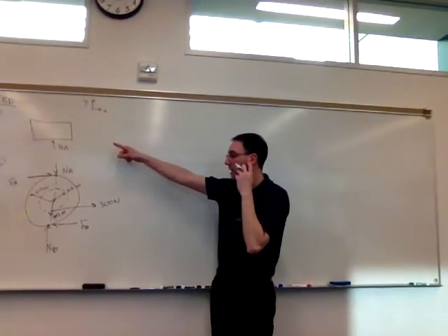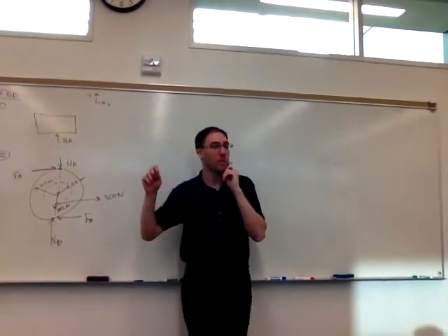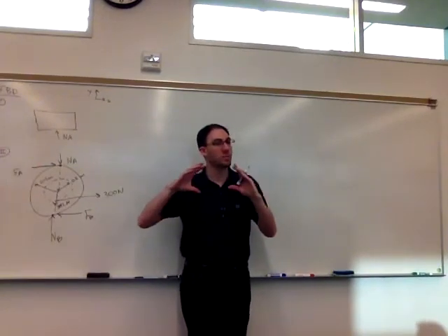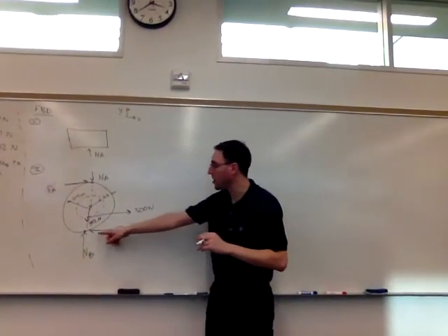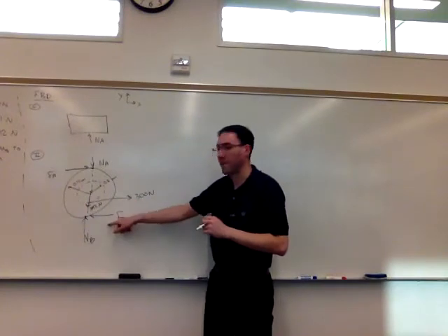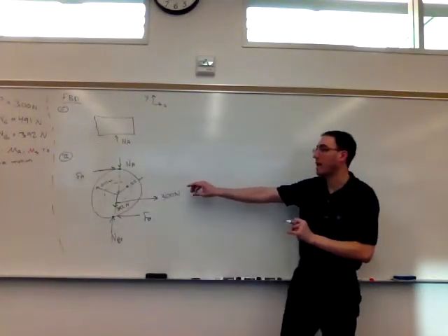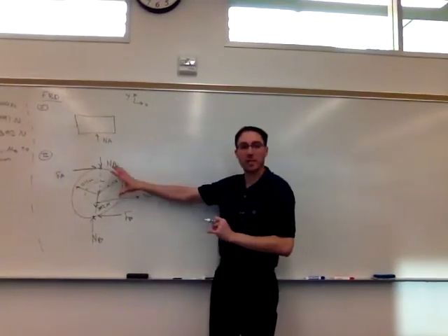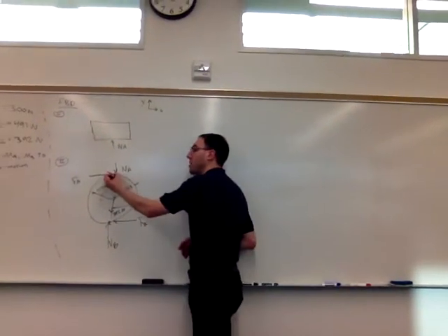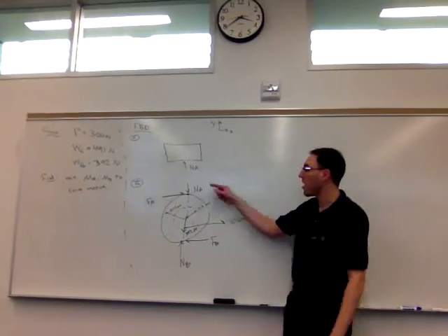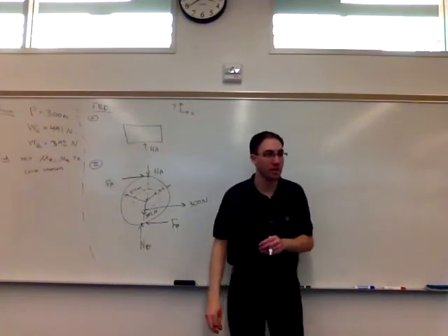Before I go back to picture one, think of the other way that we thought motion could occur. The entire spool slides to the right, in which case, what direction should the friction point at B? Right, it should still point to the left if the whole thing is sliding. However, at A, if the whole thing is sliding without rotating, now this point wants to move to the right. Therefore, the friction will be pointing in the other direction.